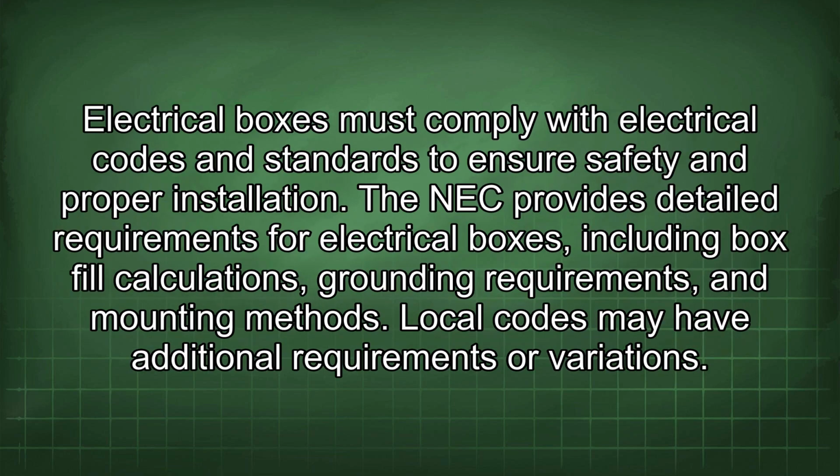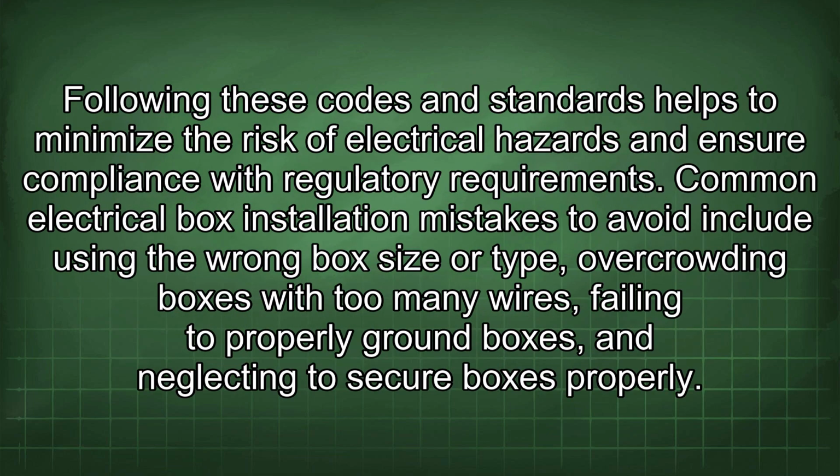Electrical boxes must comply with electrical codes and standards to ensure safety and proper installation. The NEC provides detailed requirements for electrical boxes, including box fill calculations, grounding requirements, and mounting methods. Local codes may have additional requirements or variations. Following these codes and standards helps to minimize the risk of electrical hazards and ensure compliance with regulatory requirements.